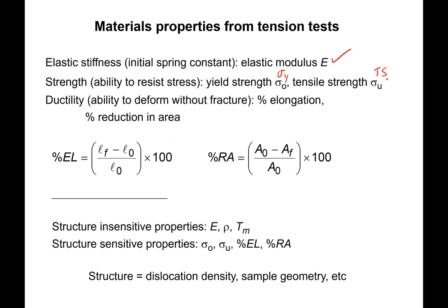The ductility can be defined in terms of that percent elongation at failure. Right? So we just saw a case for 37%. The ductility could also be measured in terms of a percent reduction in area. Okay, so how much did the sample change in cross-sectional area? So that's a measure of ductility. So we can actually put some numbers to ductility now, instead of just referring to a sample as being ductile or not ductile.